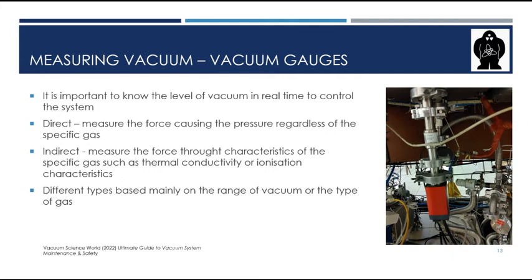As with vacuum pumps, there are many options based on the exact requirements. I will talk in more detail about Pirani and Penning gauges later, as they are used at tokamak GOLEM. Additionally, they are the most commonly used gauges because their combined range is from 10^5 to 10^-7 pascals.